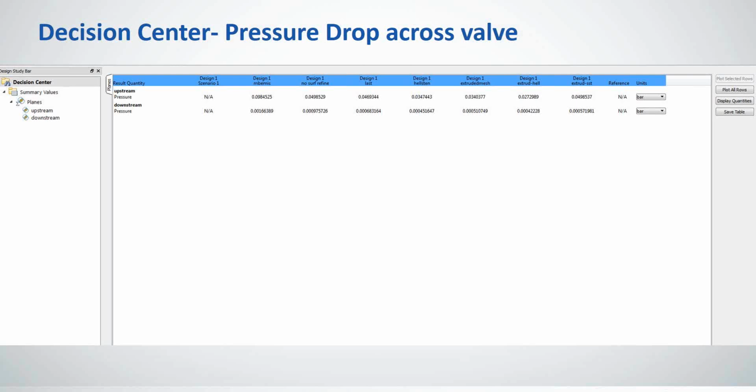So again, here I tried I think 8, and at one point there were more than 8. And again, you can see my planes. I named them upstream, downstream, and we started crunching the numbers to look at pressure drop in bar, and finally got a very good result. Less than 10% in a symmetry model, which is not too shabby.